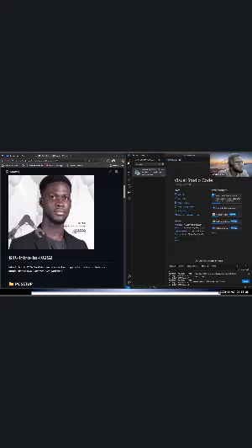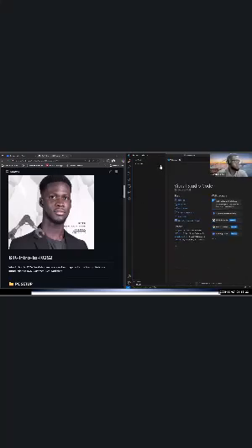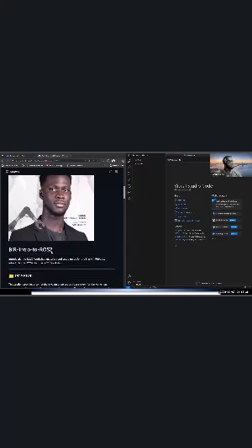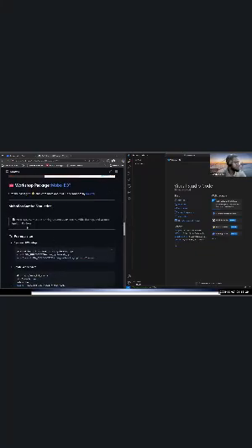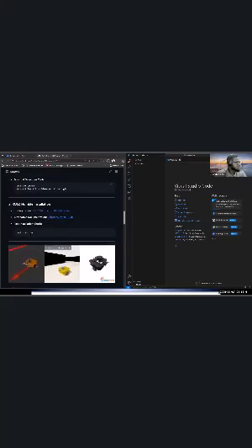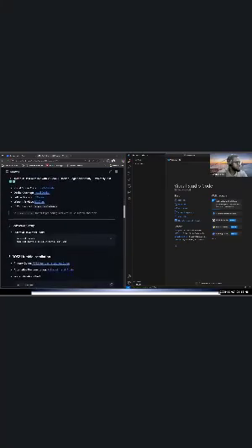So this is the VS Code, for example. It's opening VS Code for the first time. Okay, so I'm gonna cancel this. Let me just clear our timing out so you can see we can all do everything together from scratch. All right, so PC setup. After you've done the PC setup, maybe later in the workshop, what you need to do is, so this is where we are. After you've installed ROS2 and your computer and development software, the first thing we're going to do is our post-installation check, the ROS2 version.